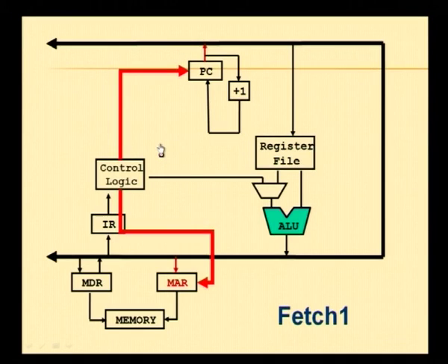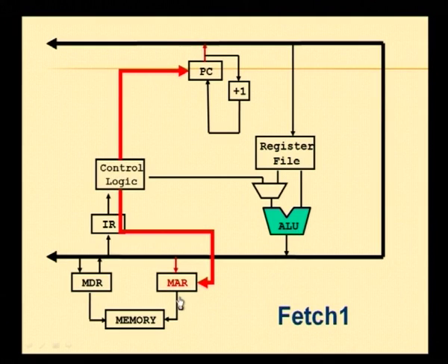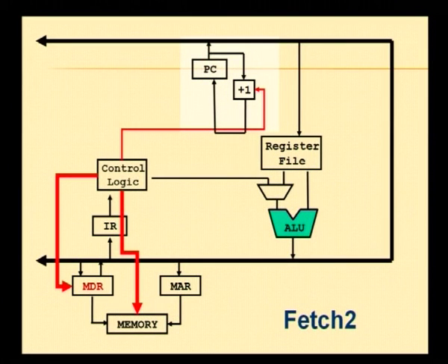Let us take the simple case. The first step is our fetch. Remember what is going to happen here in the fetch step. Add R1, R2, R3 has not yet come into the picture. We have to fetch the instruction first. So, to fetch the instruction, the control logic gives control to the PC and to the memory address register. First step done. Second step of the fetch itself: telling the memory unit to take the address from the address register and produce the output in the data register.